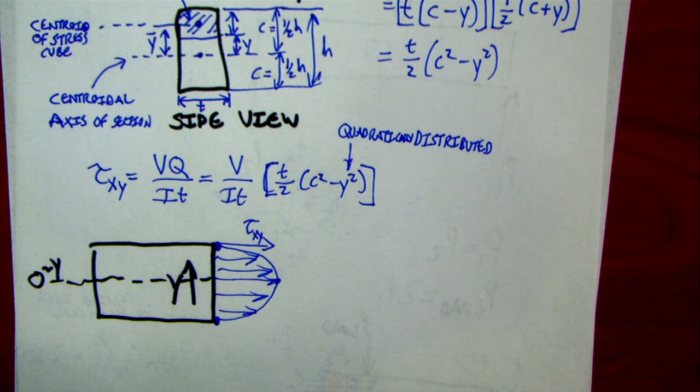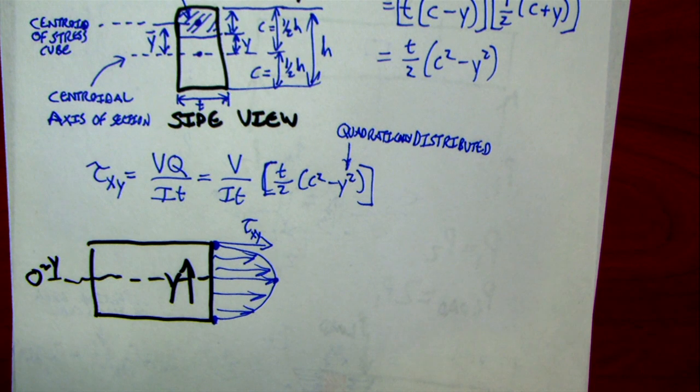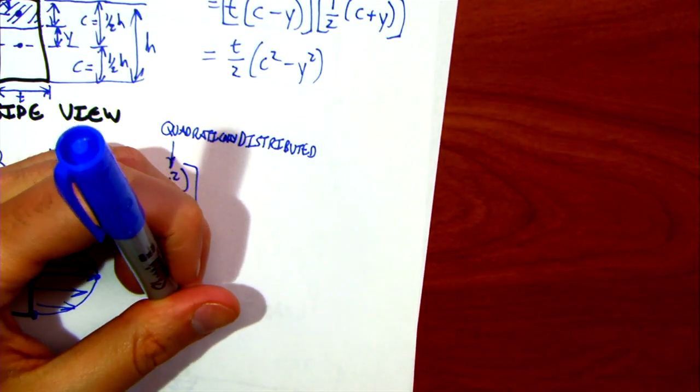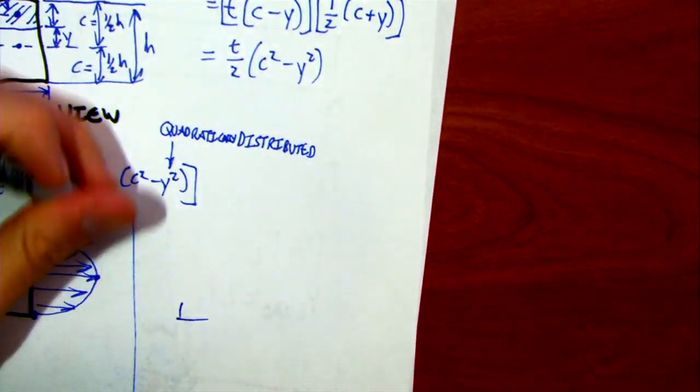Shear stress will not give you as much stress as bending will, but because of Mohr's circle, we have to account for how it's distributed in order to get an adequate estimation of the stresses on your member. So let's try a thought experiment here. Say that I had an I-beam.